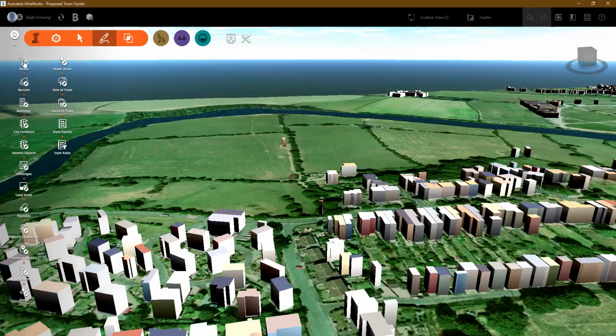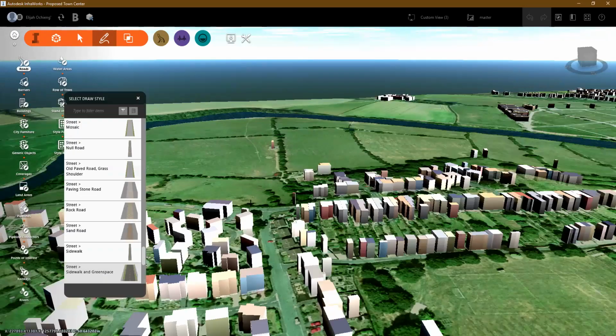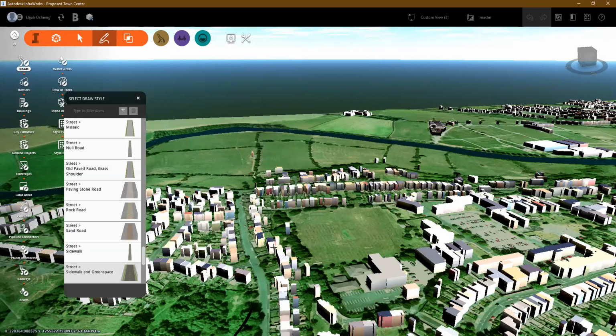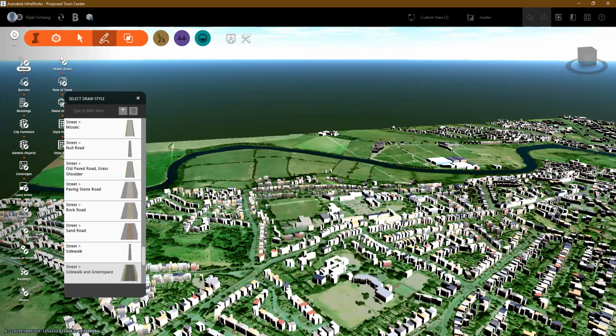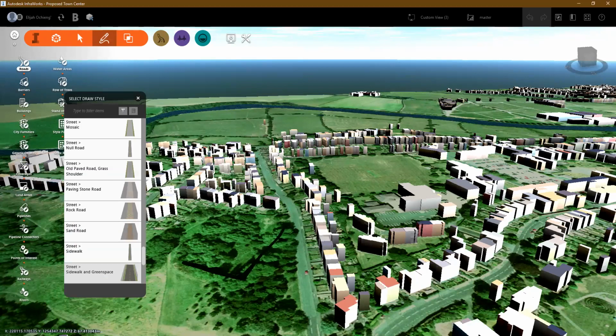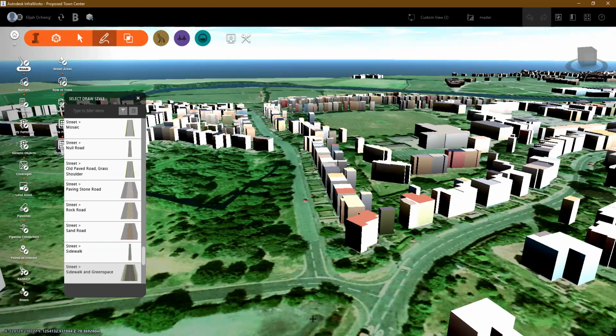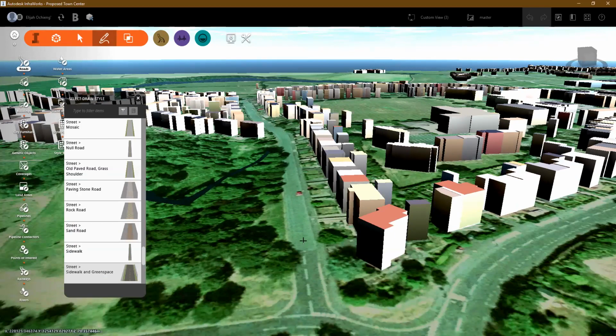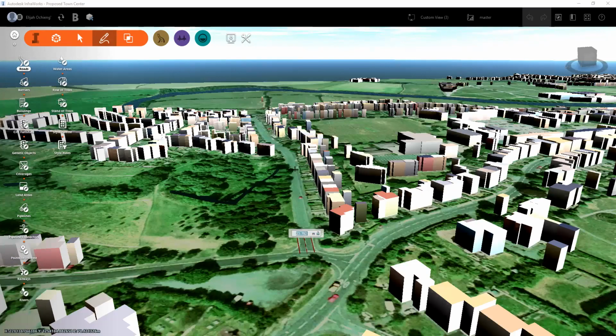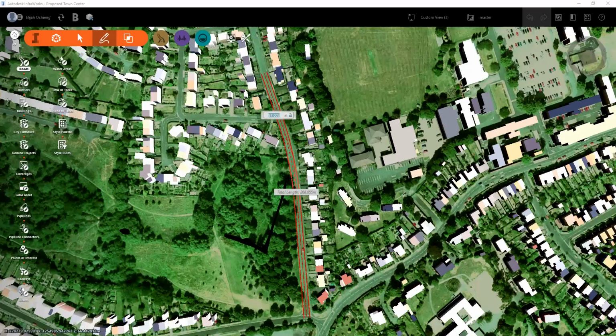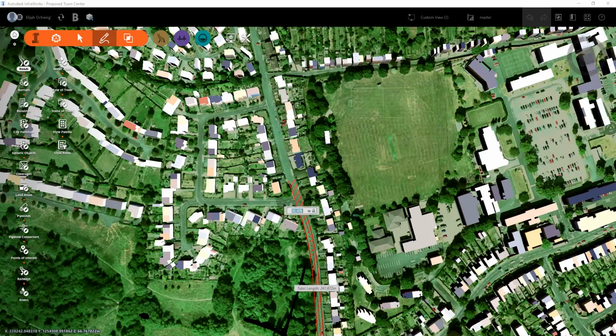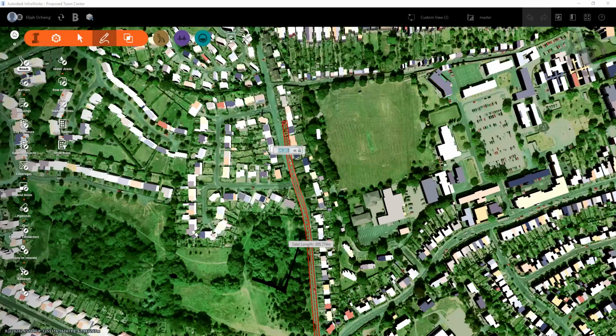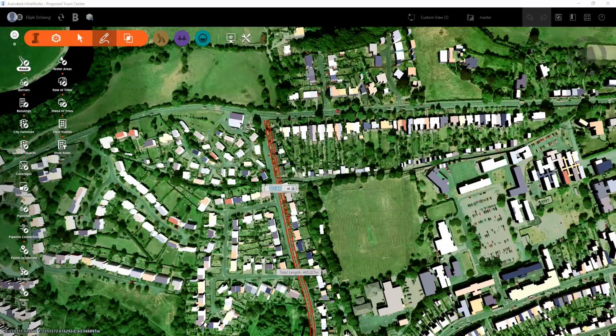For this purpose, I won't go into that detail, but I'll just illustrate how we can start by sketching our road within a proposed corridor. So I'm having this corridor here, which I want to do a road. Currently the road which exists there is 2 lane, 1 in each direction, but we want to upgrade it to dual carriageway, 2 lanes in each direction. InfraWorks makes doing that concept very, very easy in terms of using the 3D road layout tools, where as I lay it out, I'll be able to see the various lengths, the curves that I propose to have, following a specific predefined route for the road.